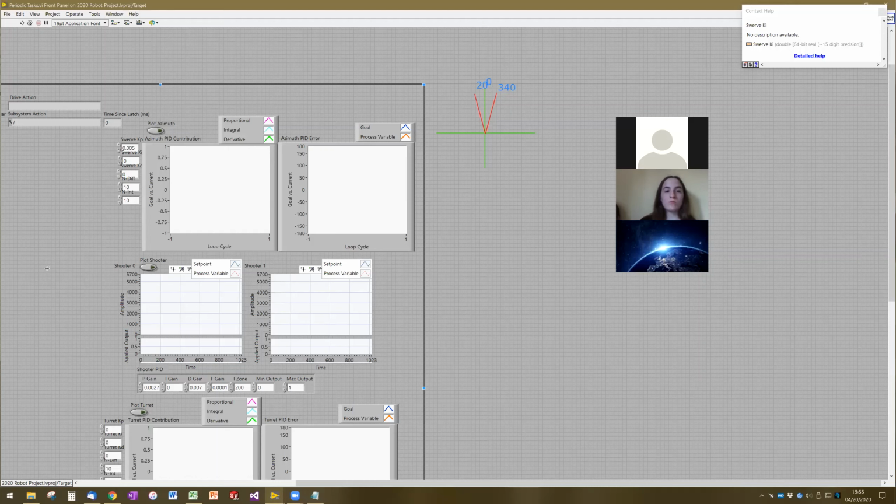The other challenge with tacking on an integral component to this is because our goal is always changing, the driver's always moving to different locations, most likely the integral would never really come into play because we'd be constantly resetting, or the integral would no longer be meaningful because the accumulated memory of the error isn't really accurate because our goal is constantly changing. So we would end up with a lot of lag in how we remember the steady state error as the driver tries